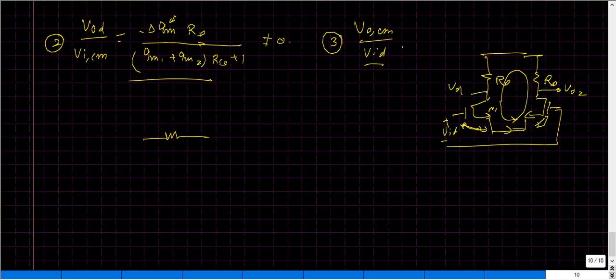In order to measure what current flows across these two source terminals, I can do it by looking across the source terminals of M1 and M2. Clearly when I look towards the source terminal of M1, I would have an impedance which is nothing but 1 by GM1, and all the resistances like RO1 I'm going to consider as a very large value and then drop those values here. And when I look towards the source of my M2, there is a resistance whose value is 1 by GM2, and we know these two resistances will basically connect between the source and the gate terminal.